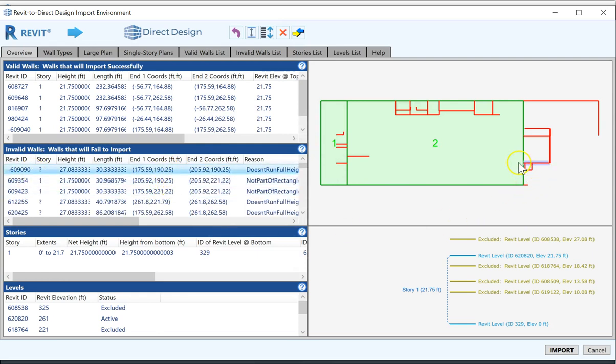Now the last problem is that we once again need to make the wall height conform to the story height. So we'll use this third button again, and now all four walls around the perimeter of this third little section are the correct height. They tie into the story height, and we now have 3 legitimate building sections that can be imported.